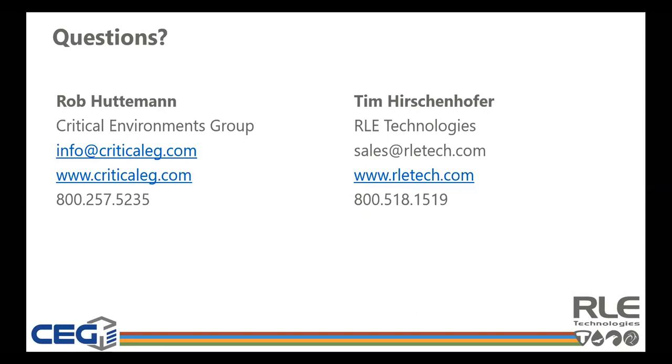Well, I'm not a fire suppression expert, but typically the plenum space is considered, from a fire containment standpoint, already a fire monitored space. If you're blowing air into the plenum, you're going to have fire suppression systems in your data center that are equipped to deal with that. So typically, just adding additional raised floor or airflow panels in the space does not require that you do anything different with your fire suppression system.